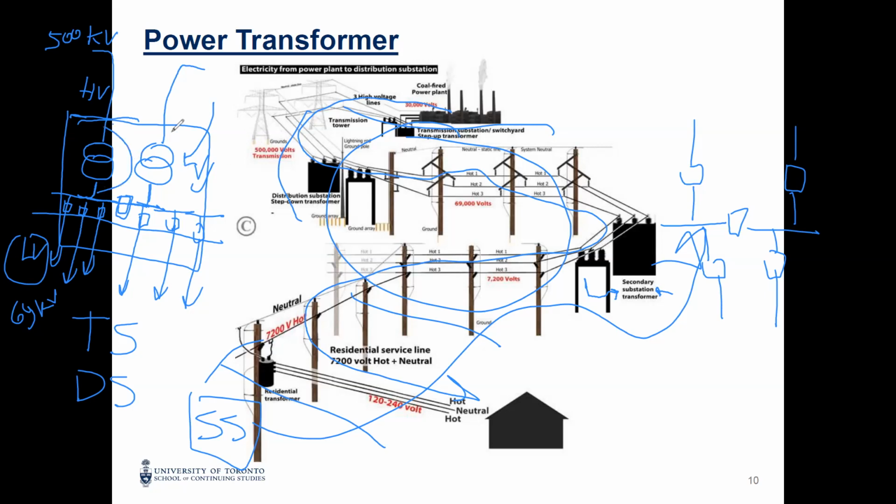It can take a lot of protection scheme, because you can have some kind of flow back on the transformers. So you want to make sure that when this breaker is closed and they are in parallel, the power is going to the low voltage and not going between the high voltage and low voltage in case something happens in the system.